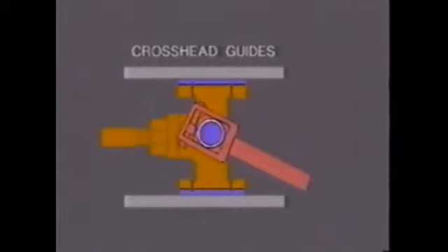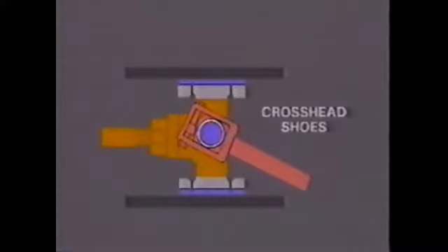The crosshead travels horizontally and must have limited vertical variation. Its confinement is maintained by the flat or circularly bored crosshead guides. Inside the guides, the crosshead shoes maintain the vertical position of the crosshead. While the shoes are replaceable and adjustable, shims on both of the shoes provide additional adjustment.